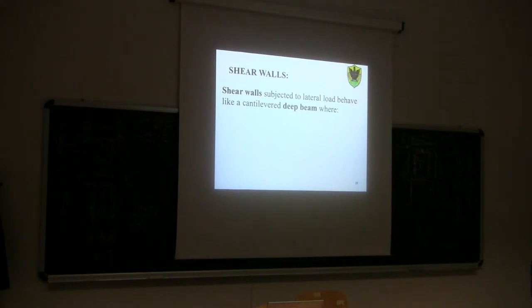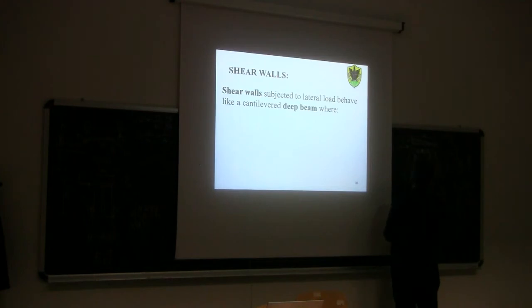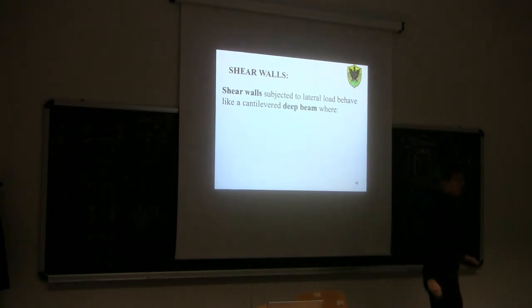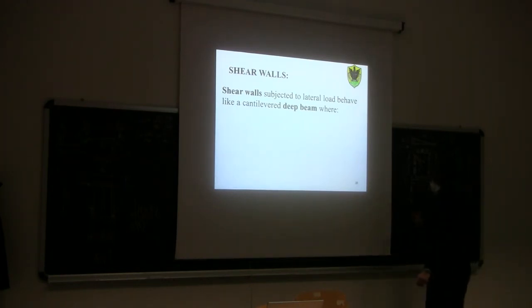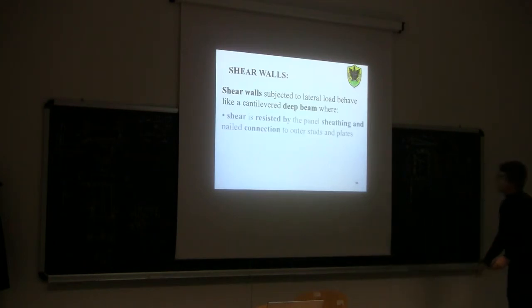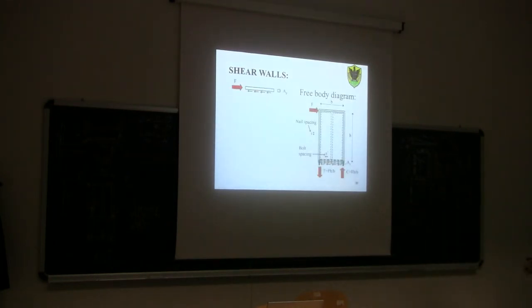And then to finish the problem, we still have some bolts here, on the lower part, connecting the bottom plate with the foundation. If we indicate with S prime the spacing between the bolts, then here, let's use the same symbol, I think it's FVD, for the bolts. Let's go see if it's the same symbol so we don't make mistakes.